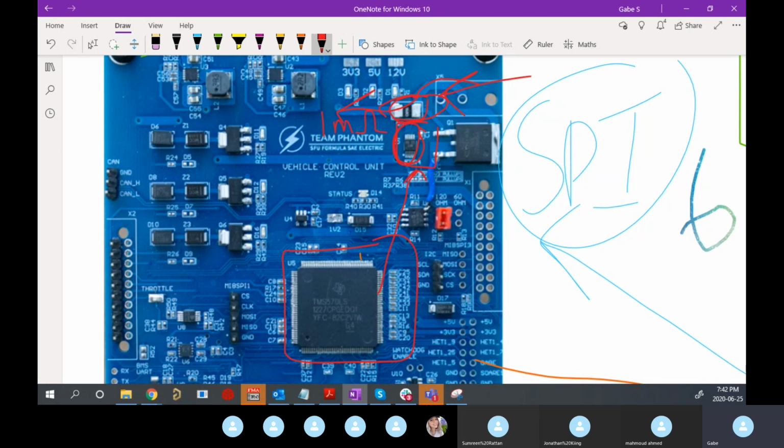It doesn't output SPI. And it's nice because I2C is low pin count, and we're using SPI in 2 different applications already on this chip. So theoretically it has 5 available, but we use I2C in this one. And it's just defined by the chip, right? This is the chip we wanted to use, and it does I2C. Luckily, our TMS570 can do I2C as well, so great, that works.